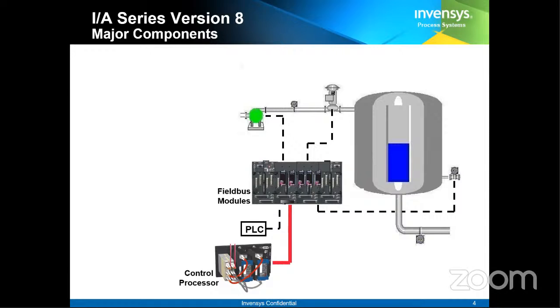If the error comes down, the output also comes down. But with proportional control alone, you will not be able to achieve the output of a control loop. For example, if I'm saying here with the level tag, if the level goes above 80, it will try to close the valve. If the level goes down, it will try to open the valve in this way.